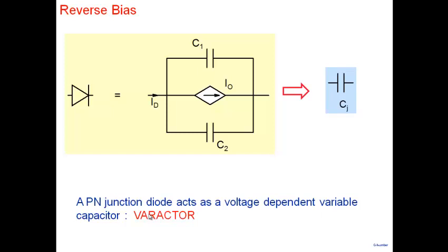Anytime you have a capacitance which changes with voltage, for example, if you have an oscillator, the oscillator's frequency will usually be 1 over R times C. And therefore, C is something that you can change with voltage. And therefore, it allows electrical tuning of frequencies and things like that. So that's a very useful property. Varactor diodes are there, and you can buy them commercially in the market.